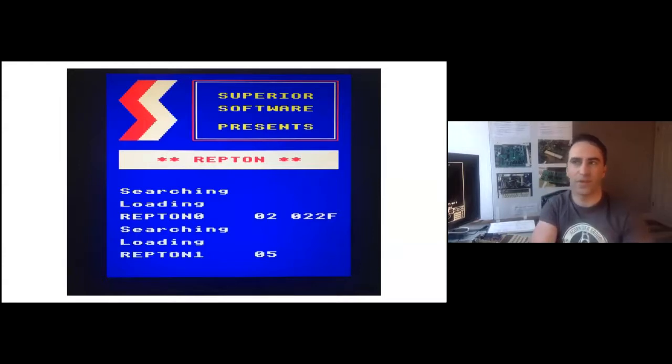It's a relatively complicated protocol, but I managed to drive it. The FPGA runs it, it's got a 96 megahertz clock, and weird stuff happens when you try to do external interfacing actually at the clock rate of the FPGA, which I'll talk about later if we've got time. But so I just did all the interfacing at half the clock rate of the FPGA. So 48 megahertz, that works just fine.